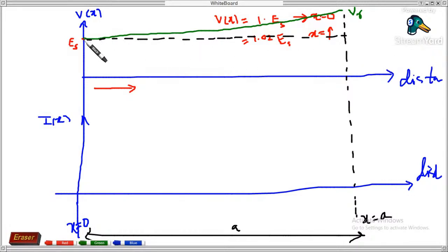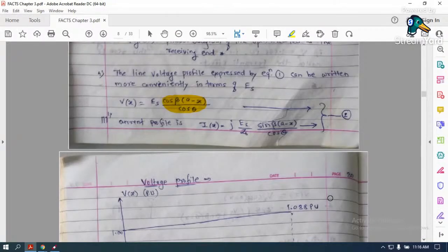Now you can see the magnitude of Vs and VR. VR is more than Vs. This is what the Ferranti effect is. Fine. Now one more thing, I proved this. Earlier you said both would be approximately equal, Vs was equal to VR, but no, VR is greater.